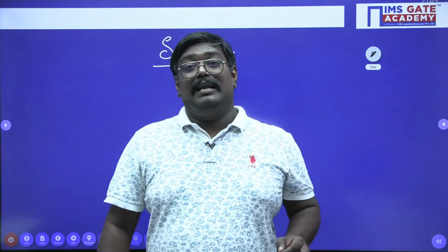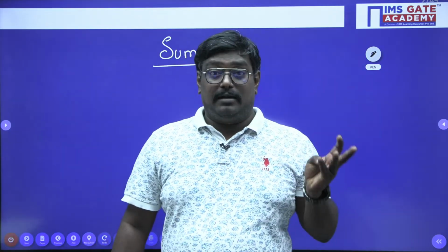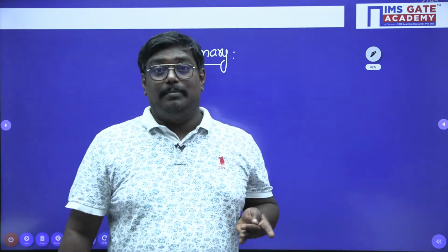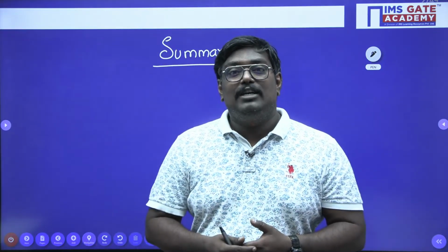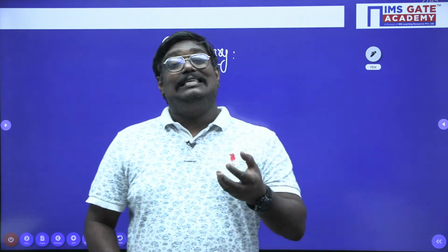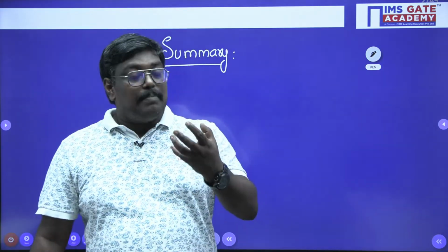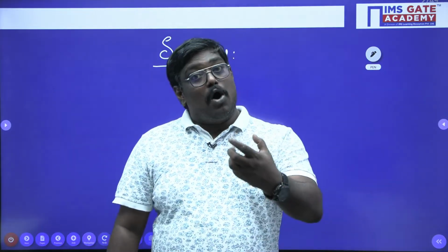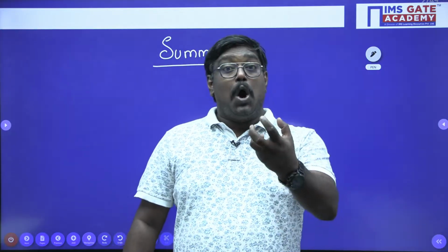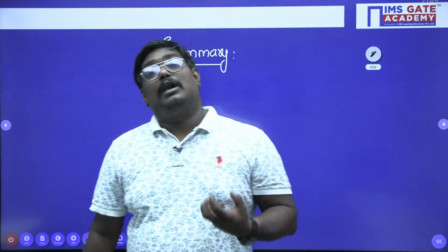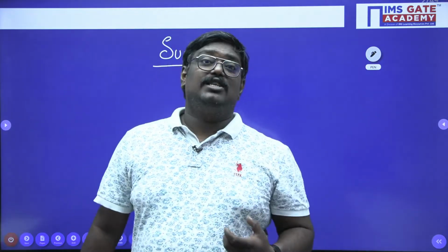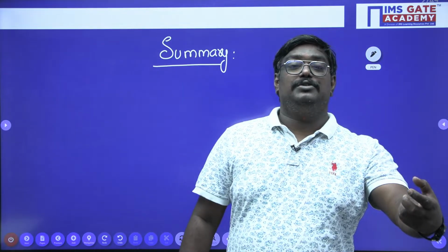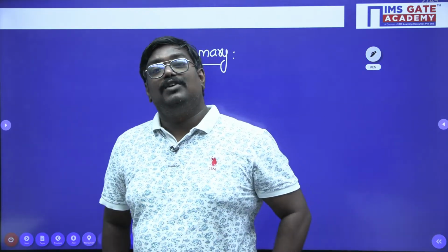In group index, my dear students, it is based on how much soil is passing through 75 micron, the liquid limit and the plastic limit. When you talk about the Unified Soil Classification System, it was devised by Casagrande on the basis of grain size distribution or particle size distribution, or you can say plasticity characteristics or compressibility characteristics. And the Indian Standard soil classification system is derived from the Unified Soil Classification System. And the plasticity chart is very important, students.